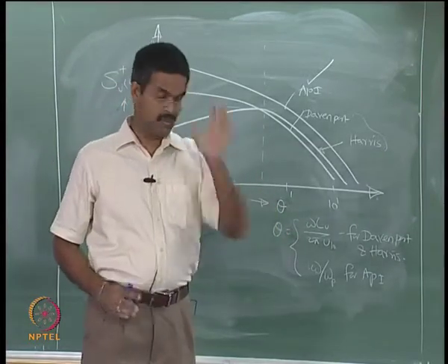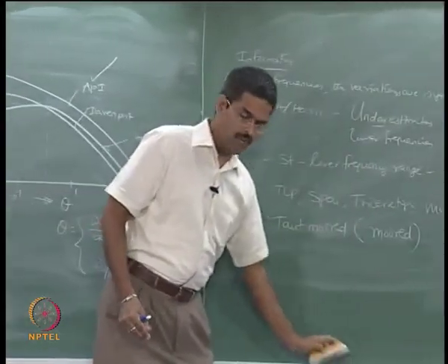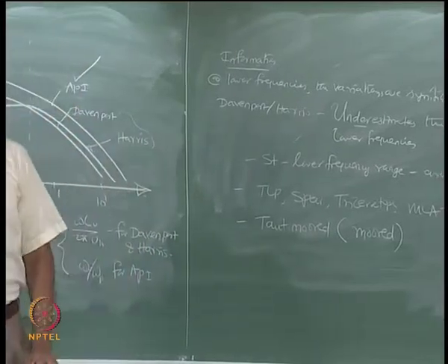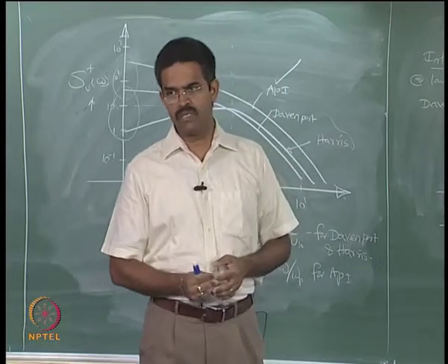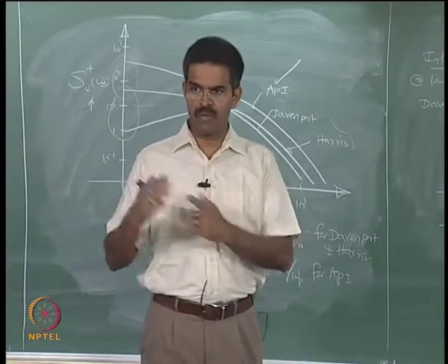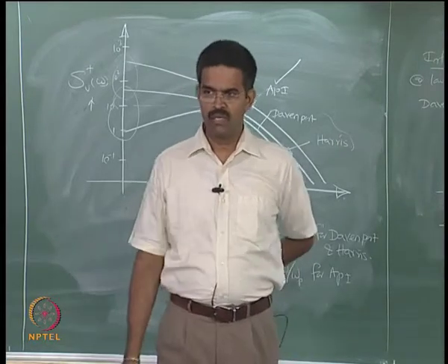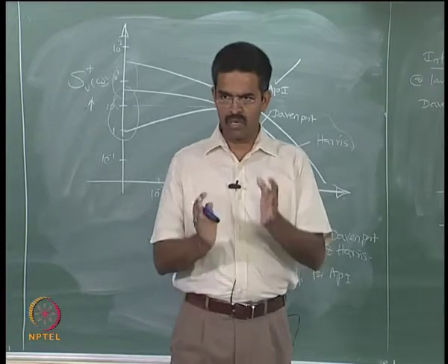So this will be the discussion we will wind up with for the wind forces on marine structures. We have now discussed aerodynamic loading. We have understood that aerodynamic loading has two components. One is the mean component of the wind velocity, the second is the gust component, which is the variable component that can cause dynamic effects on the structures. The static component, the mean wind velocity, will not cause dynamic effect, it causes static effect.